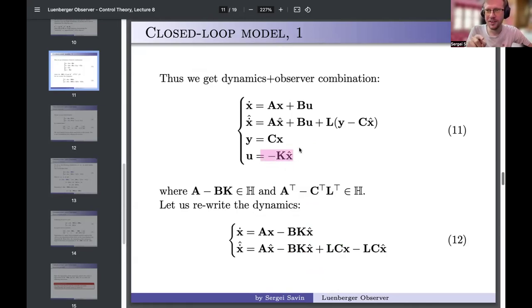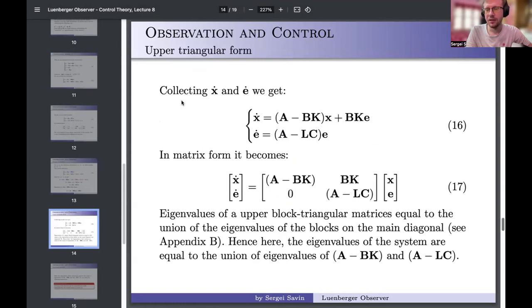Even so, we still get our eigenvalues in terms of x the same as we got them at the design stage. So eigenvalues of the x coordinates are preserved. Right? Same about the observer. So as long as you're willing to think about optimality in these terms, as we designed the system for just a controller without regard for observer, and we get optimal controller gain, which gives us some eigenvalues. Well, those eigenvalues will be preserved.